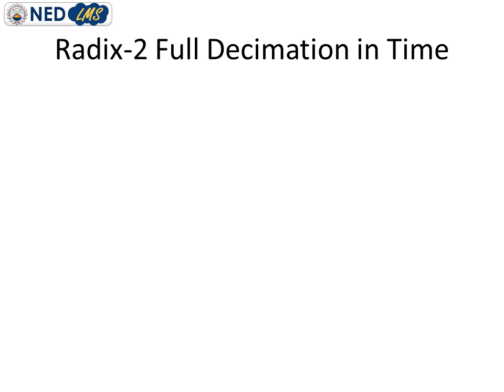But you know that it will degrade the quality of our output as we are omitting our original sample values. So it is not a much efficient technique. Another technique which we can implement for this issue is zero padding. Zero padding is basically appending a number of zeros so that your sample set becomes equal to 2 raised to power k.